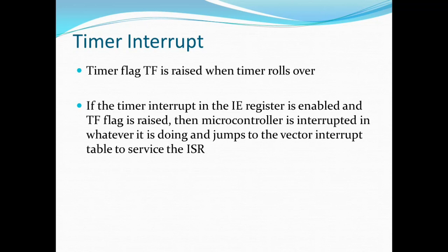So the important thing here is that you have to first enable that particular timer interrupt through the IE register. You have to load a particular format in the interrupt enable register, and only then will your microcontroller get interrupted.